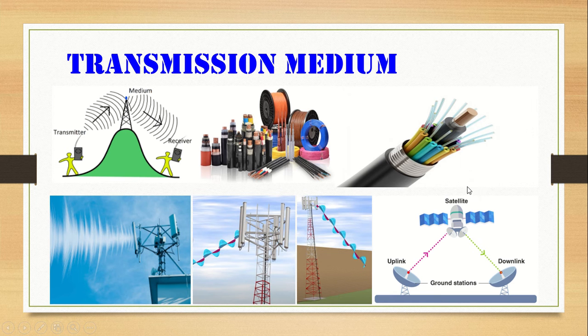We have the uplink. We have here the transponder. So it means transmit and respond. That's the meaning of transponder. The purpose is to receive the signal from the Earth, then transmit back to Earth. So there will be amplifying and processing here, because a geostationary satellite is about 36 thousand kilometers from the ground. Naturally, the signal from the ground, when it reaches there, is already very weak. So it will be amplified and then sent back, or reflected back, to the Earth.